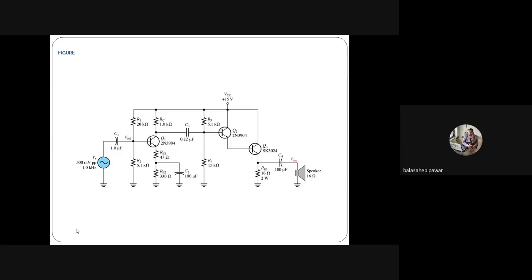Now we will design and develop another amplifier using another device, like an OPAMP. You already studied the OPAMP as an inverting amplifier and non-inverting amplifier. Over here, as it is in CE configuration, we are calling it an inverting amplifier because, as I showed in the previous slide, there is a 180-degree phase shift between input and output. So we'll configure the same amplifier, that is an inverting amplifier, using an OPAMP, and we'll set its gain in such a way that it can process that 100 milli or below 100 milli.